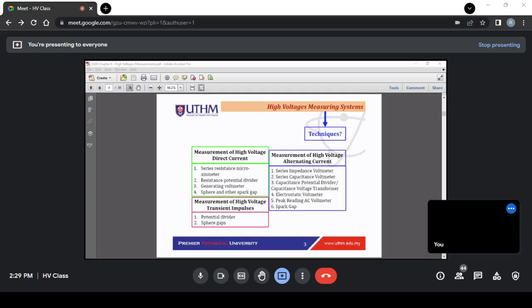And of course, the disadvantages, apart from being heavy and permanent, are the voltage ratio. Because we are dealing with mega ohms level and high voltage, the voltage ratio is something very sensitive, and they are vulnerable to temperature variations, because when we are talking about high voltage, there will be current flow, and the current flow will cause Joule heating.